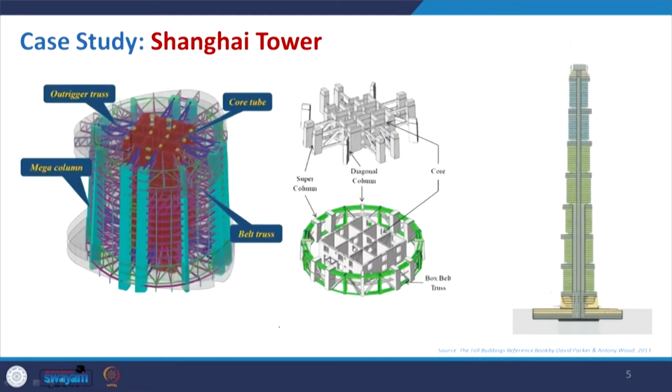Coming to the structural system, as we have discussed earlier in the examples of exterior structure and interior structures, the structural form being used here is the core tube structure. So, tube structure, if you recall what we discussed recently, is where you place the columns at very close intervals and then they are connected with spandrel beams. So, that will form a tube.